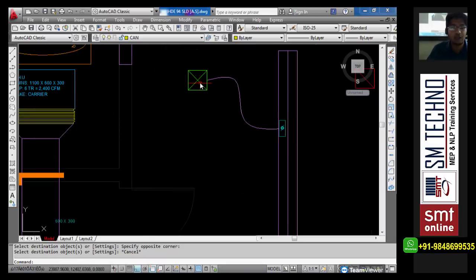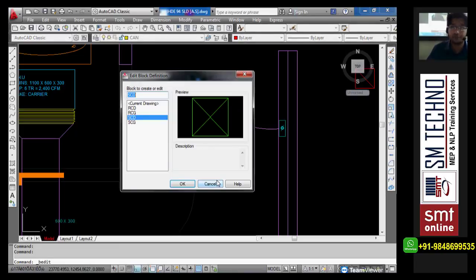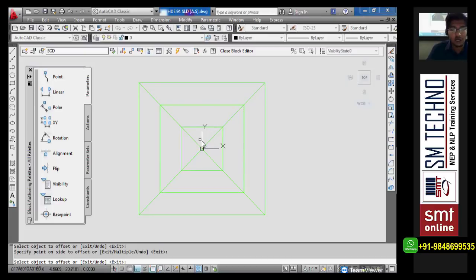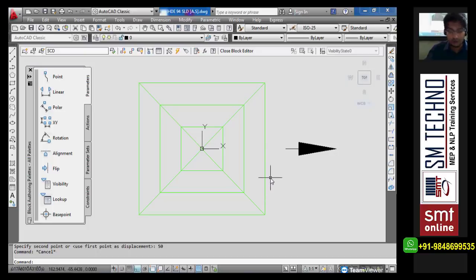Now we know that we have created this yesterday in block. So I can just double click that to edit in the block editor. Go there. We are going to convert that into the actual SLD. So take the offsets inside. Lastly, we need PL enter to create the arrows. Width is already applied too much, make it less, then give the arrow indication for the tail first, then W enter, starting with maintaining 30, the other one 0, lastly 90. Move for a displacement of 50 mm.